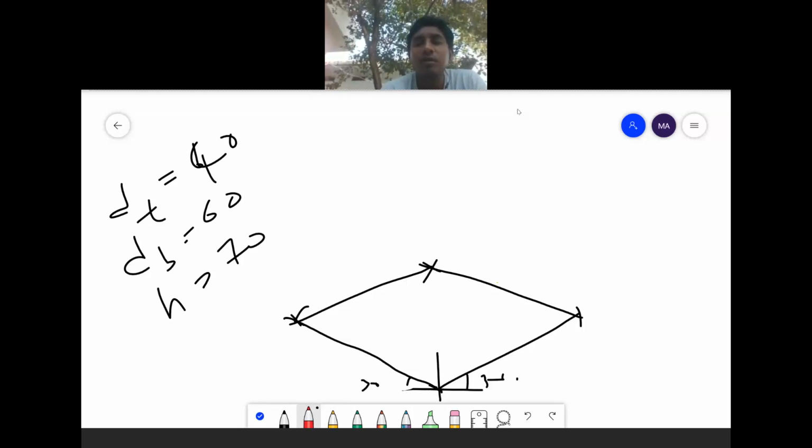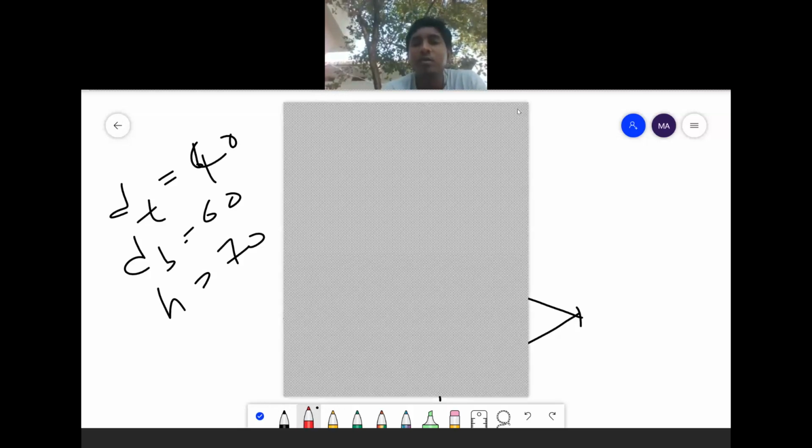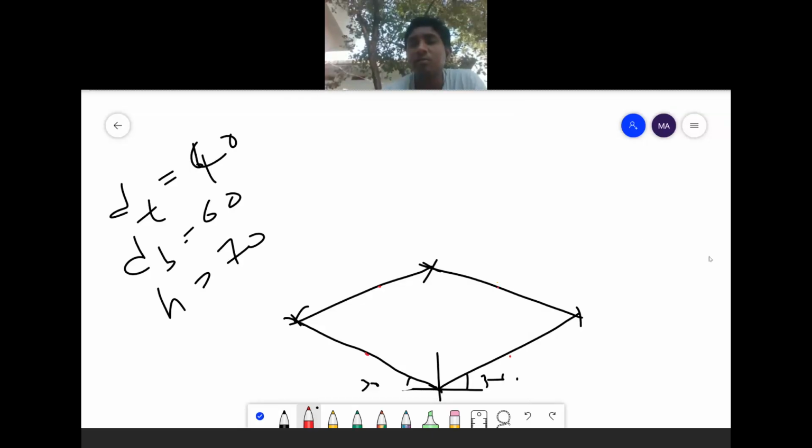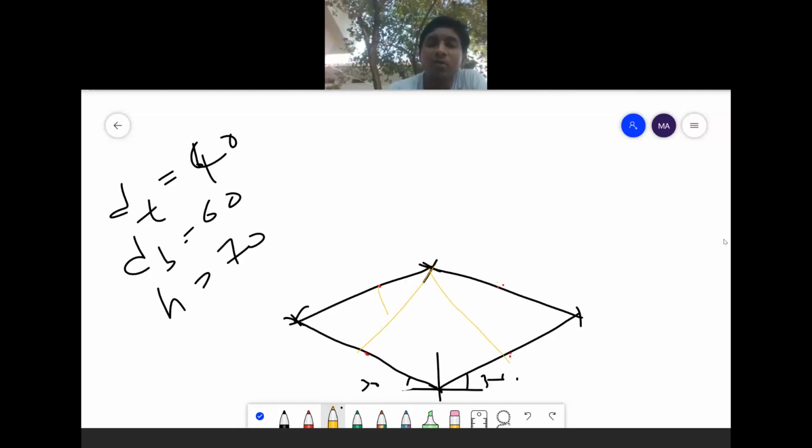Using the four center method, I am drawing the circle here. I have marked the 4 centers here. Each center is at 30 mm, the midpoint of the given side. Then I am joining from this top vertex to this line and bottom vertex to these 2 points.